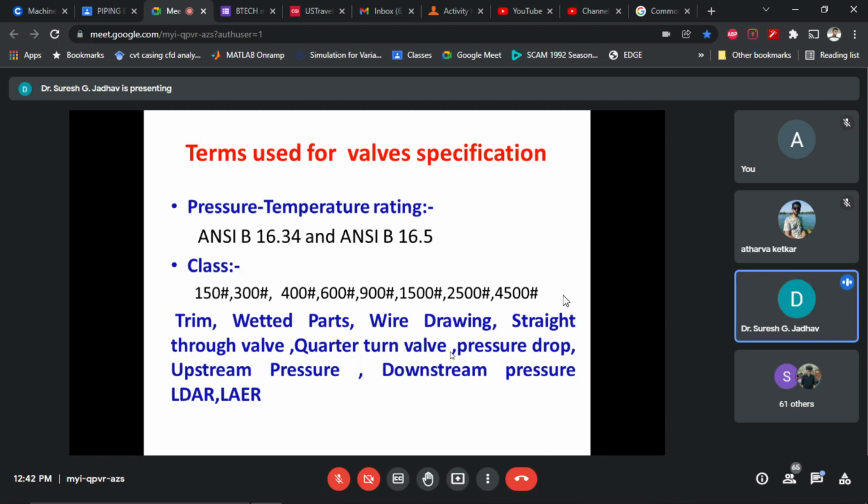Why is it the best defense? Because its resilience makes it easier to close tightly. Discs of harder material have to be closed carefully to prevent wire drawing. In LPG services, liquefied petroleum gas services, the wire drawing effect causes a threat of auto-refrigeration.